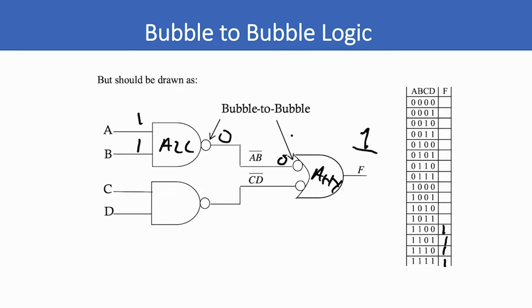Okay, let's look at this. Let's look at the second input to this gate. Or this says we can have a 0 here. So if we have a 0 there on the other input to this NAND gate, we can have a 1 on the output. So how do we get a 0 here? Well, to get a 0 here, this says all inputs high, so C, D. 1, 1 will give us a 0, and when we get a 0 here, any 0 gives a 1. So anytime C and D are both 1, we're going to get a 1 out.